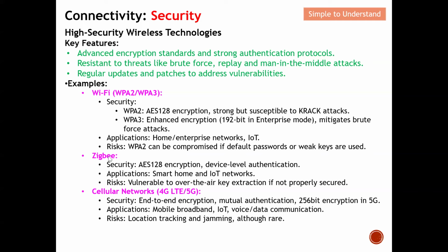For Zigbee here, Zigbee is also using AES 128 encryption. Basically they have device-level authentication, which means the device will seek authentication from the Zigbee coordinator. If you can, look at the Zigbee video to understand more. As for the application, Zigbee is widely used in smart homes and some IoT networks.